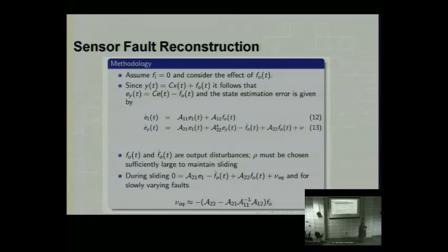And that's really common because a lot of the faults that are difficult for fault detection people, so they tell me, are really slow drifting faults. This is a big problem. If you have a big problem with a massive rate of change, usually you can tell by many means. You don't necessarily need a sliding mode observer. Much more difficult is the very slowly varying incipient fault that's in there drifting over a period of time, where for a long time, for example, you might not see any effect at all.